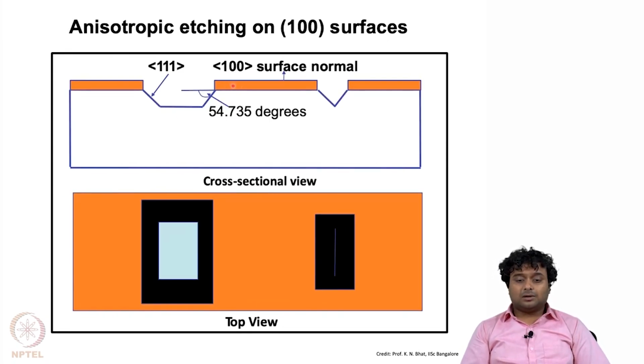So, this will not allow the silicon to get etched below it, and this can actually be silicon dioxide. So, we can put silicon dioxide on according to our design. How we can do that using lithography, we will discuss in some other class, but the point here is that silicon dioxide can act as an etch stop or the protective layer or the masking layer.